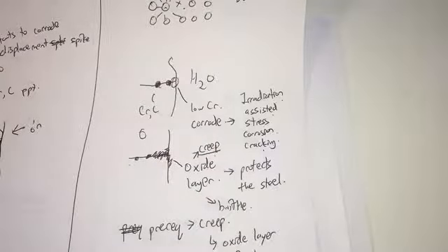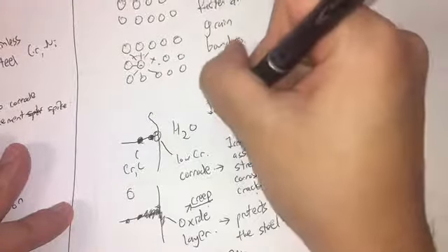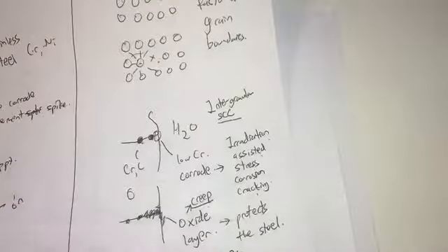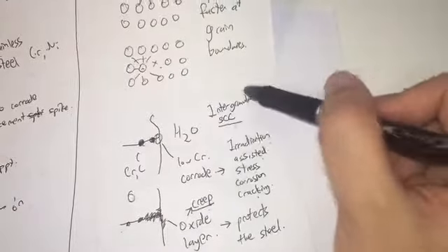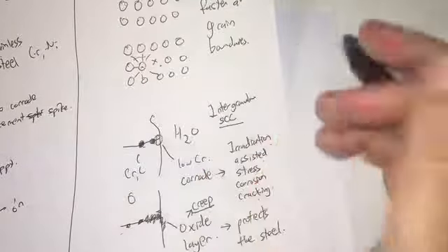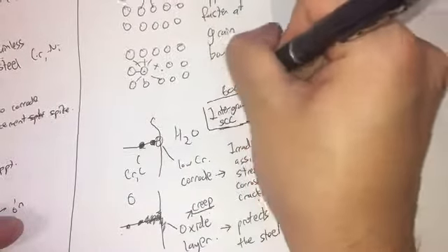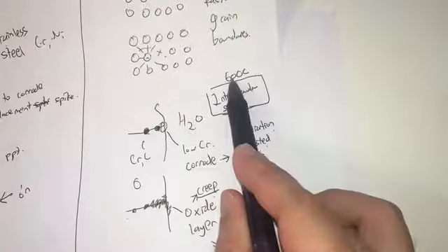Yeah, this is very similar to something called intergranular stress corrosion cracking. So I just use SCC to represent stress corrosion cracking. But the main mechanism, if you have heard of this before, causing this to occur is temperature, which causes something similar to this to occur. And that requires around 600 degrees C for the precipitates like this to form, because you need some kind of activation energy.